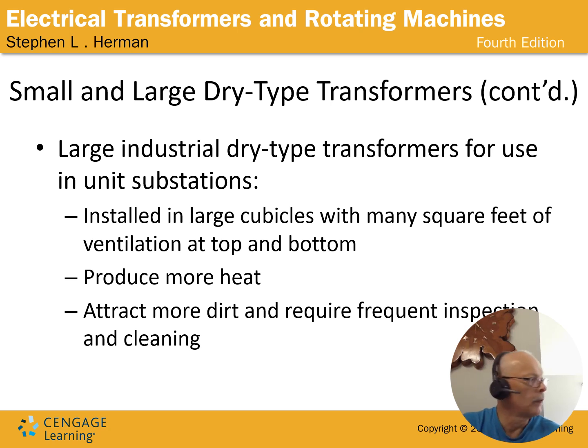If you have it out in the open, there's a lot of air, but if you have an enclosure, even with air holes, that air has to be channeled and it can't move as fast. So once again, dust and dirt will want to stick to it. They build up an electrical charge around the transformer and will begin to cling stuff like static electricity, and you have to brush that off and clean it up if you notice it.